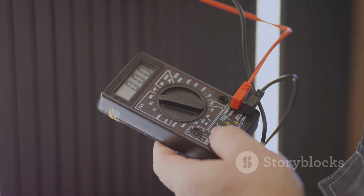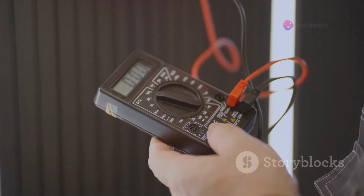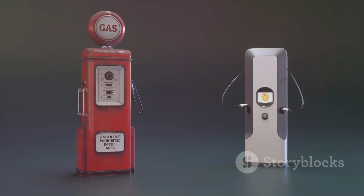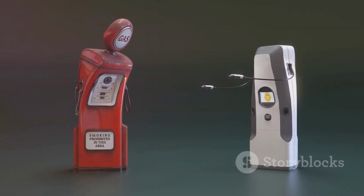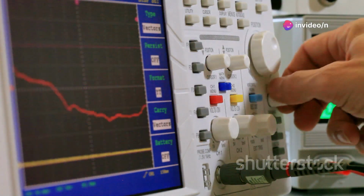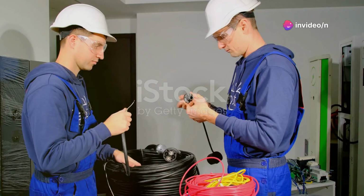RMS current. Similarly, RMS current is the equivalent DC current that would produce the same amount of heat in a resistor as the fluctuating AC current. It's the average current that delivers the same power as the AC current. In essence, RMS values give us a way to compare the effectiveness of AC and DC sources in terms of power delivery. It's a way to translate the fluctuating nature of AC into a more steady, comparable value.